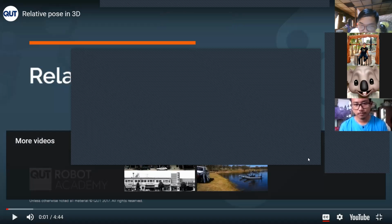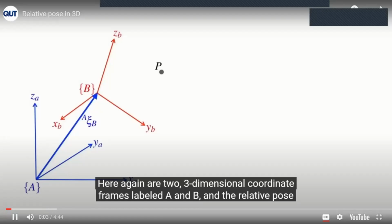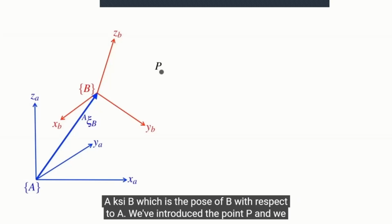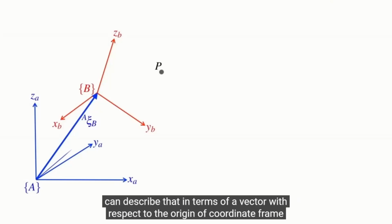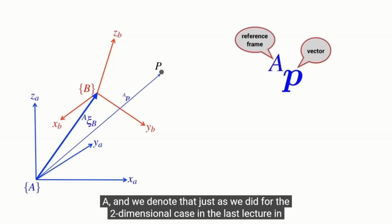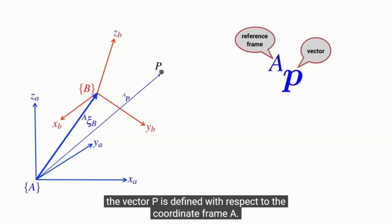Here again are two three-dimensional coordinate frames labelled A and B and the relative pose A psi B, which is the pose of B with respect to A. We've introduced the point P and we can describe that in terms of a vector with respect to the origin of coordinate frame A, and we denote that, just as we did for the two-dimensional case in the last lecture, in this fashion where P indicates a vector and A is the reference frame that indicates that the vector P is defined with respect to the coordinate frame A.